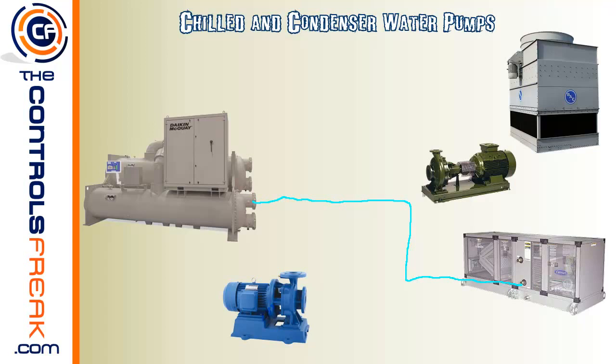The reason they do that, and it'll help you identify what piping is what, is that when you fill this coil with water, you always want the outlet of the water coming out the top of the coil. You want it to fill up with water before trying to pull it out. If you supplied this coil with water from the top, the water may not actually fill the coil and you'll get air in it, which would mean you're not going to get cooling on the upper portions of the coil, and water would flow and then come down and get sucked out the bottom. So they fill it from the bottom to make sure you pressurize the coil and get all the air out of it.